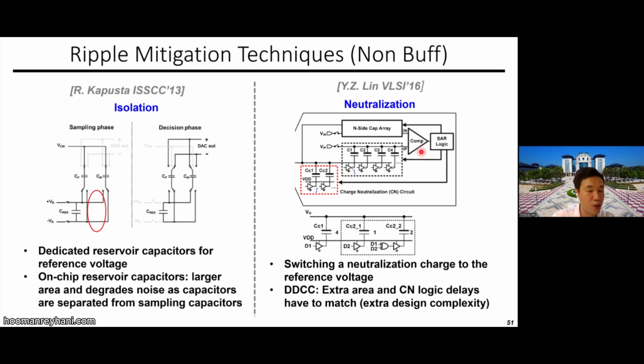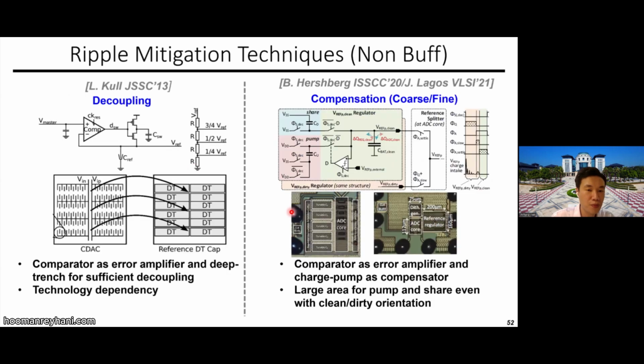So this is one of the problems, and it is very difficult to make this timing edge identical. It's because this compensation for one bit is easy, but for sequential bits, you actually need a lot of different logic. So the delay of these two cannot be made identical. Well, there's some kind of trick you can do.